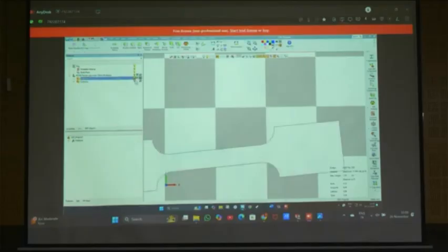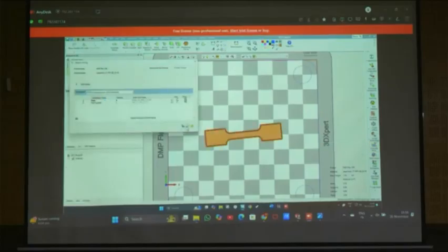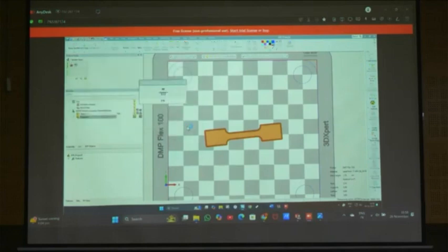Okay. So for the single body we can apply the slicing to reduce the time. So first we can go for the calculate slices, later we can define our own parameters. First we can slice with the default parameters, later we can define our own parameters. So first we'll go with the default parameters, click OK, and we are applying 17-4 PH. You can change the material also, titanium and aluminum, cobalt chromium, whatever the machine can support.